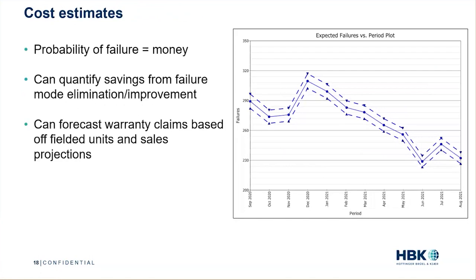So we've got a couple tools now in our toolkit that all lead us to that use level life distribution. And we now can get those probabilistic estimates that are really useful. Because if we just have the projected life is 12.7 years, we can't really say what that means in terms of money. Whereas if we have a probabilistic model, like our use level life distribution, like our Weibull distribution, we can estimate, for example, warranty claims and directly relate that to the money or the cost of reliability.